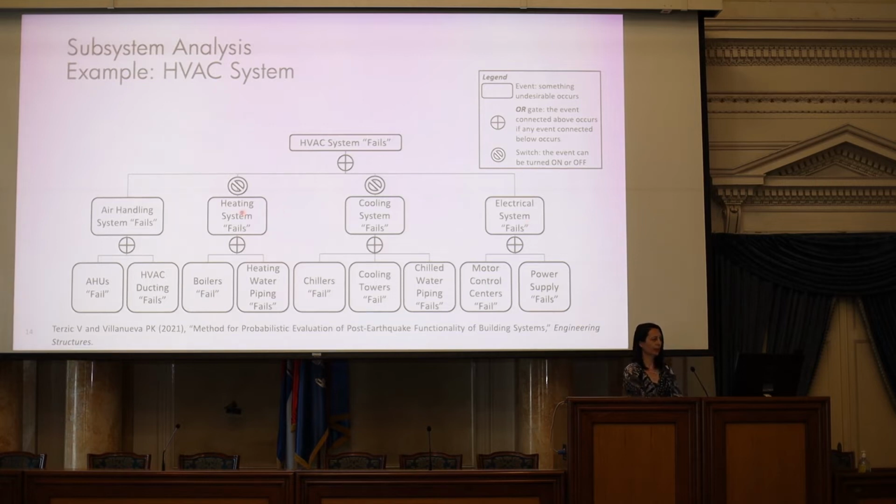In the United States, heating and cooling really depend on the season of the year and the function of the building, and they're not always necessary for the building functionality. So we're introducing those switches here, which we can use to turn them on and off from our analysis, depending on whether we need them or not. So if ventilation is the only one important, we turn off cooling and heating from our analysis.